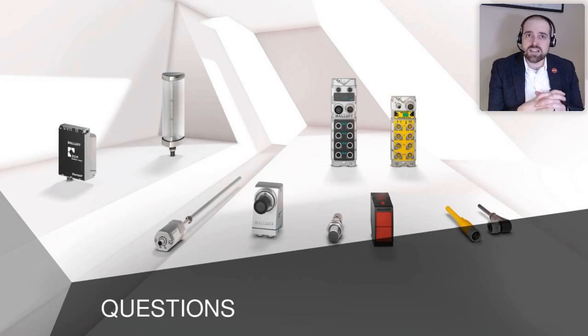And Balluff, of course, has IO-Link masters. You can see one in the center of this picture here that talk all the industrial protocols, so EtherNet/IP, Profinet, and such. So the ability to connect the condition monitoring sensor to any Ethernet protocols really, or even any PLC chassis is a pretty diverse option. IO-Link has over 300 companies in the consortium, so there's a lot of different options of technologies that can be utilized to get IO-Link connected to your machine.